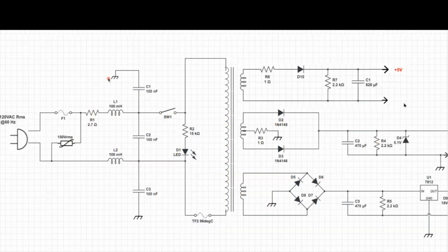Motors from vacuum cleaners, appliances, power tools can generate noise on our power line. And this noise suppression or line choke device should help clean up our power line and hopefully have a nice 60 hertz clean AC waveform going to the rest of my power supply, because that's what we want. We don't want noise and interference on that. When I say noise, that's not an audible noise. What we're saying is some sort of unwanted signal on our power line that should not be there.